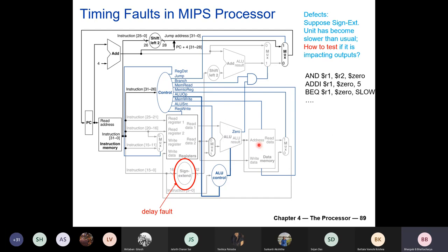So what I mean is that in the processor there may be functional defects like this, and you need to do a lot of input-output experiments. You need to execute some instruction set so as to figure out whether the processor is performing correctly. And this is an essential component in the manufacturing part. As you see, you need the understanding of instruction set architecture and at the same time the overall organization of the layout to determine your test procedure. So that's all about your processor design and how it operates, how to design the controller, and the effects of some kinds of malfunctioning.